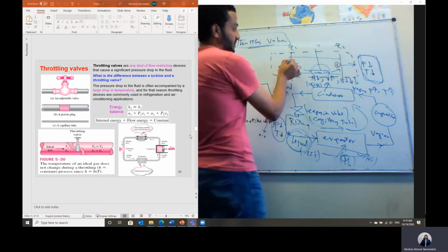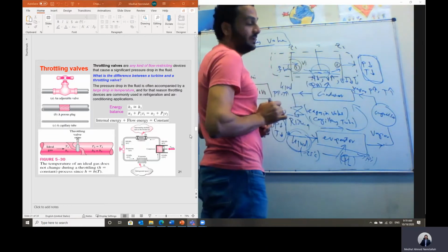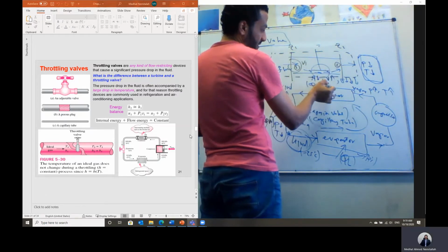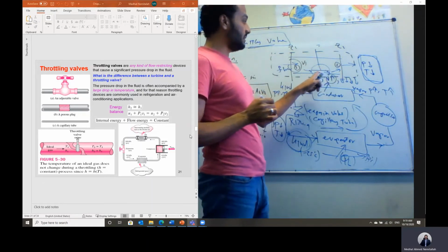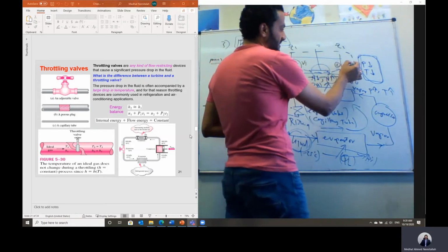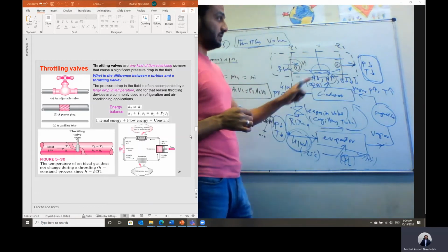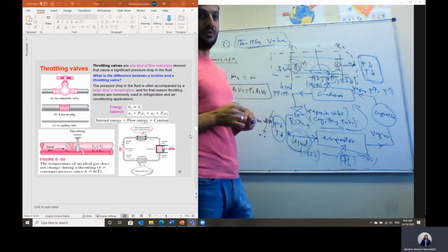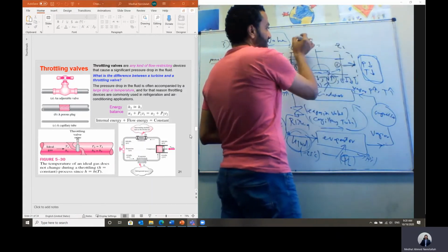Usually the flow, before coming to the throttling valve, has a velocity, let's say V1. The velocity is increased in this restriction, just below this valve, because the area is restricted. But when the flow gets back to the normal cross-sectional area of the tube at the exit section, section number 2, we can almost retain the same velocity.